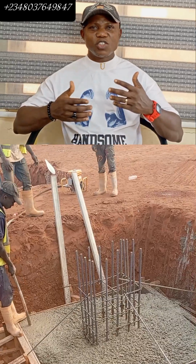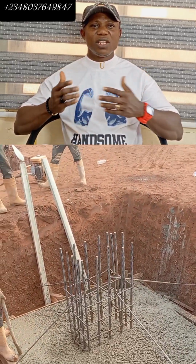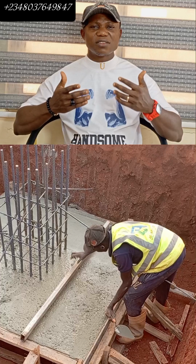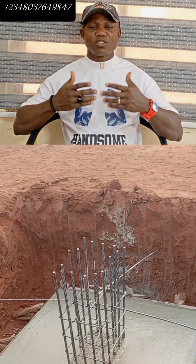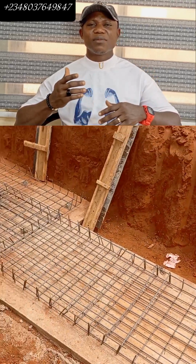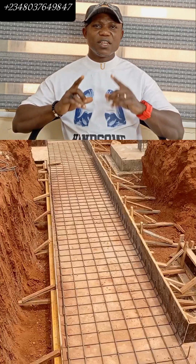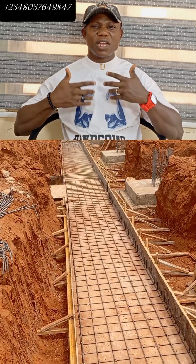Because in some cases, you might have an experience where your vendors will deliver less if you don't have an idea of the required quantities of material when you do your ordering. So you need to know how many lengths of 8 mm, 10 mm, 12 mm, 16 mm you have in 1 ton. So at the end of the calculation, you have all this information handy.